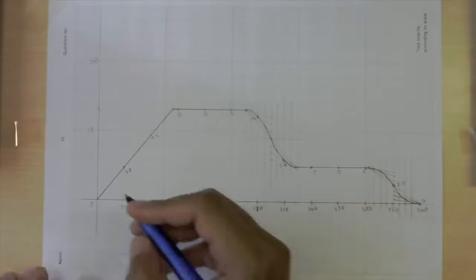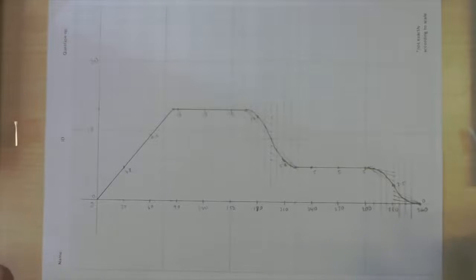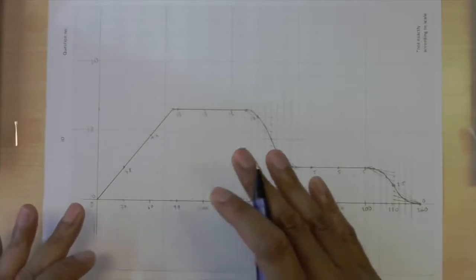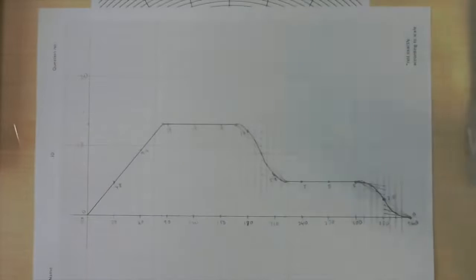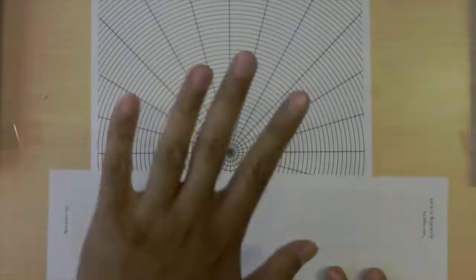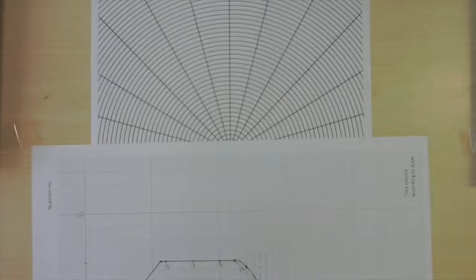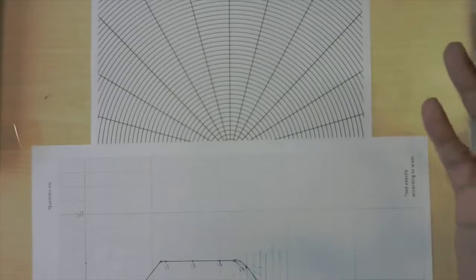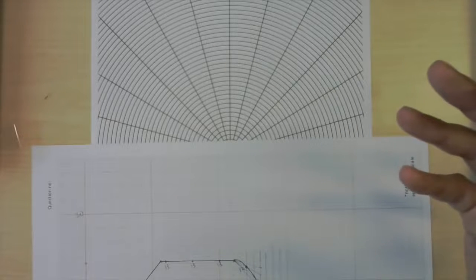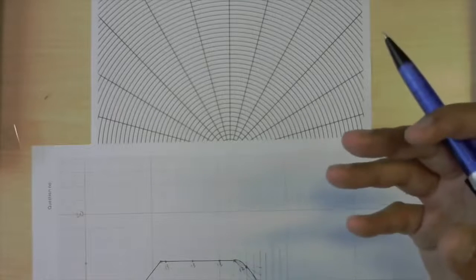Okay, now we have the full data for the displacement diagram, all the displacement at every 30 degrees. With that, we'll be able to plot on the polar paper. Then we can start to draw on the polar graph paper. Before that, since the question did not actually require you to draw a cam profile, some of the information is not actually given. For example, the direction of the rotation, and the base circle dimension and so on.